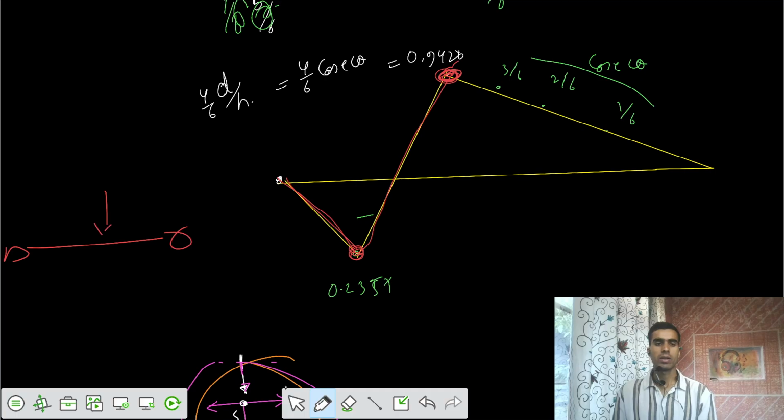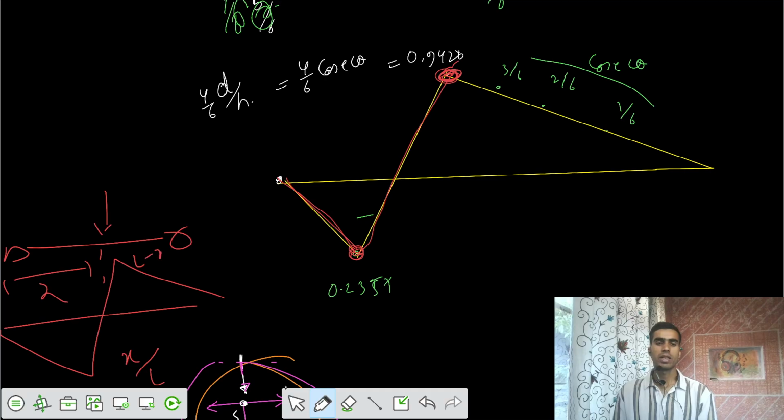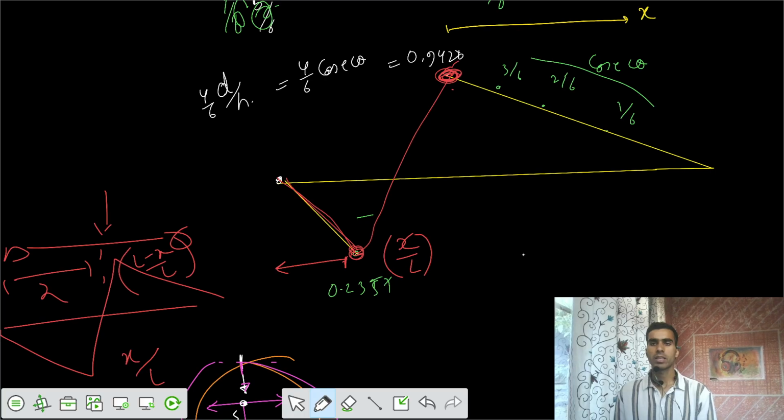So I would say the equation for this one is actually we have that simply supported beam. You have that section at x. We say that the shear force from the bottom is equal to the ILD ordinate x by L. This ordinate is L minus x by L. Similarly, for this case, this value is x by L, and this one is L minus x by L. And I say that the general equation is that you can have that x value, but in the opposite direction, this one is your x by L. And you have one more factor here, because the member is diagonal, so you have to multiply by this factor of d by h. That's the cosecant theta. So x by L, so your value of x is varying.